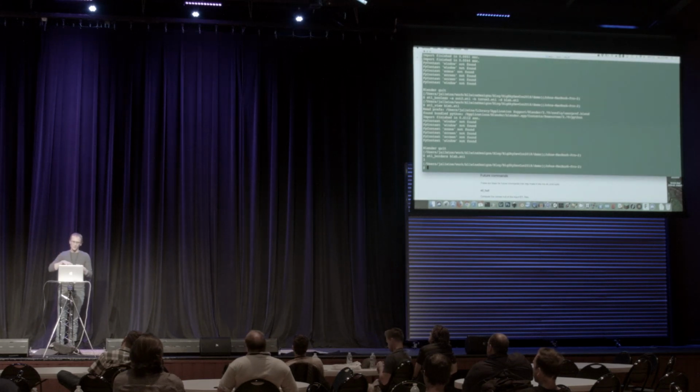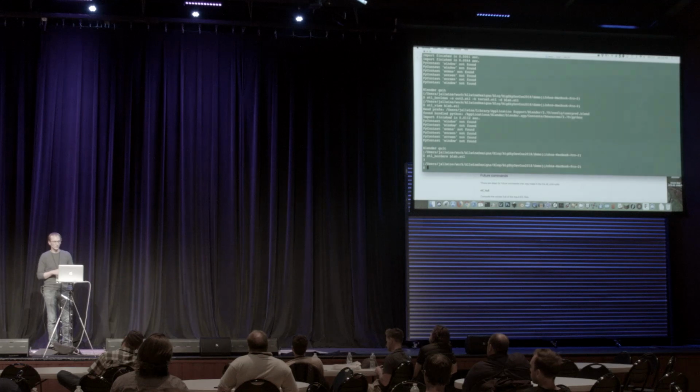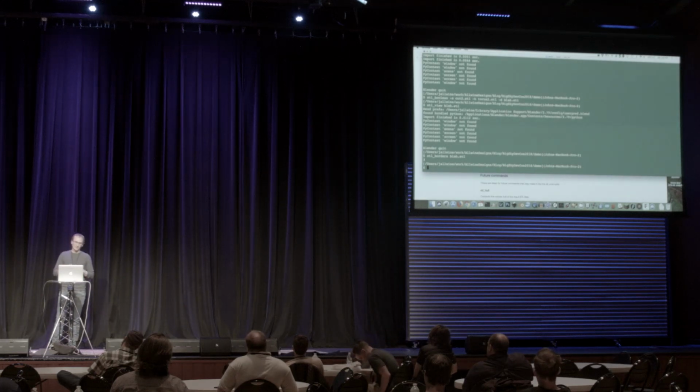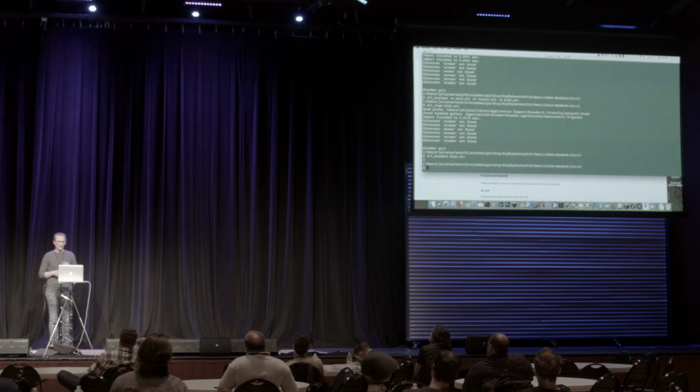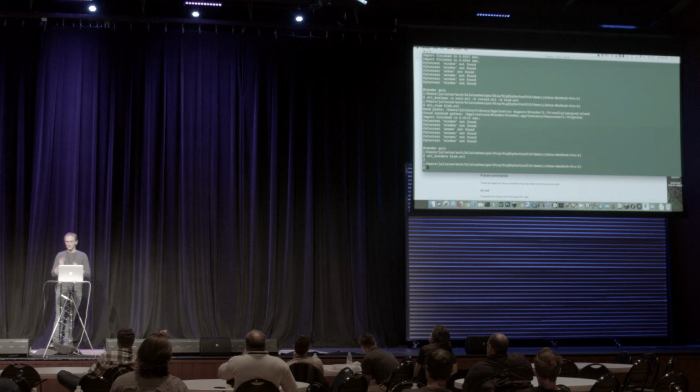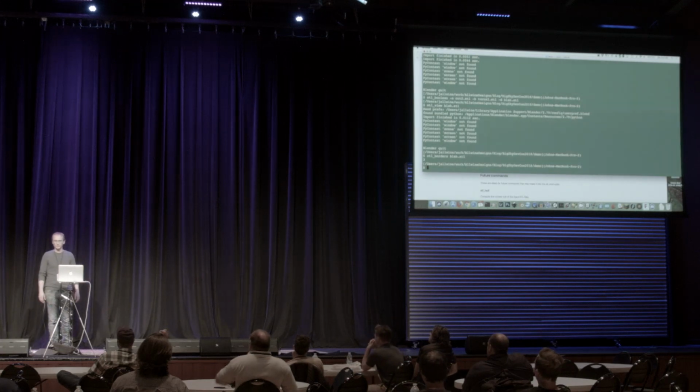And then you do that for multiple models, and it's able to very quickly recombine them and only keep the pieces you want. But when you slice things up that small, you have only a finite precision. It does it with double floating point precision, but eventually your triangles get so small that they become degenerate, or they're just so tiny you can't compute accurately.